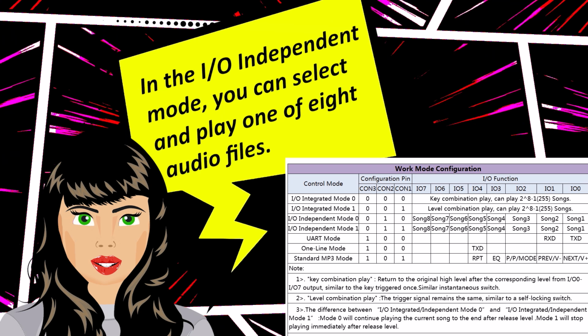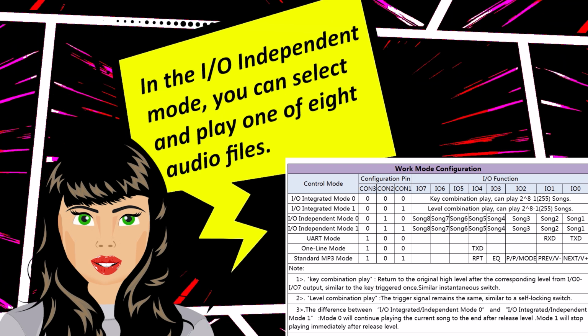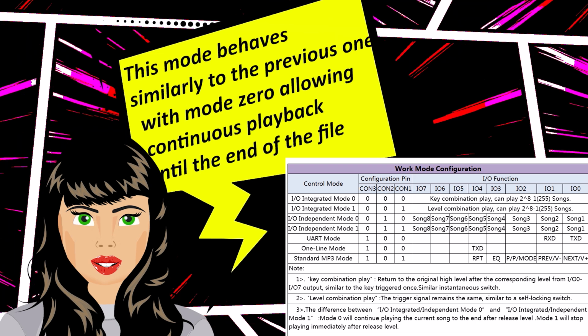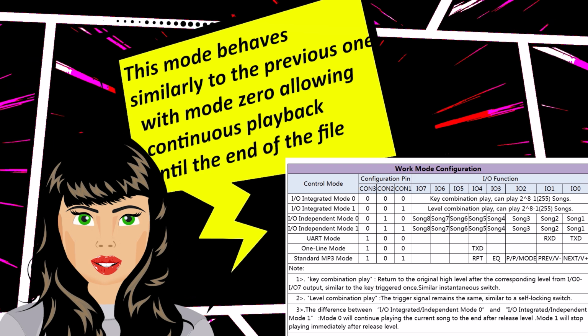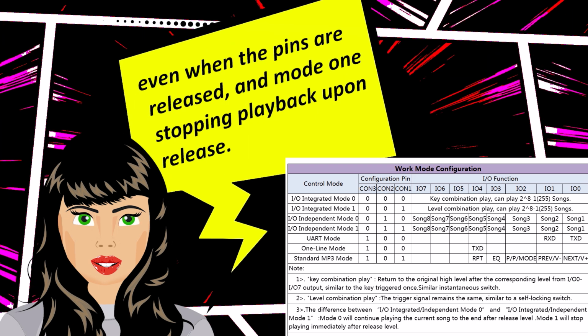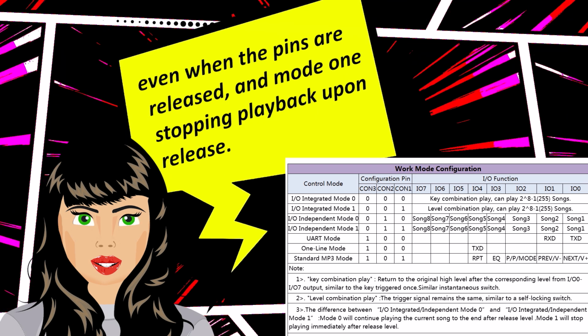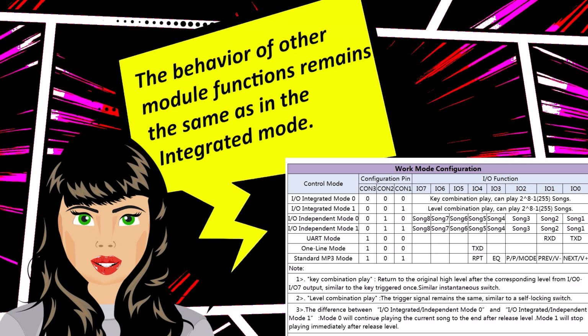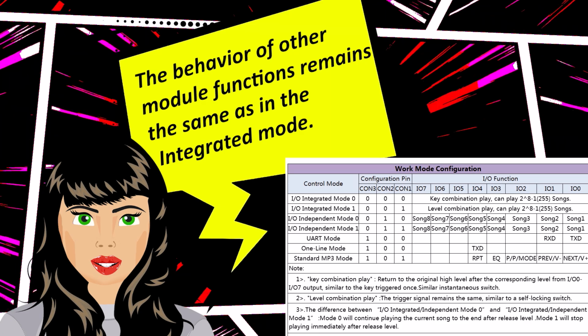In the I/O independent mode, you can select and play one of 8 audio files. This mode behaves similarly to the previous one, with Mode 0 allowing continuous playback until the end of the file, even when the pins are released, and Mode 1 stopping playback upon release. The behavior of other module functions remains the same as in the integrated mode.